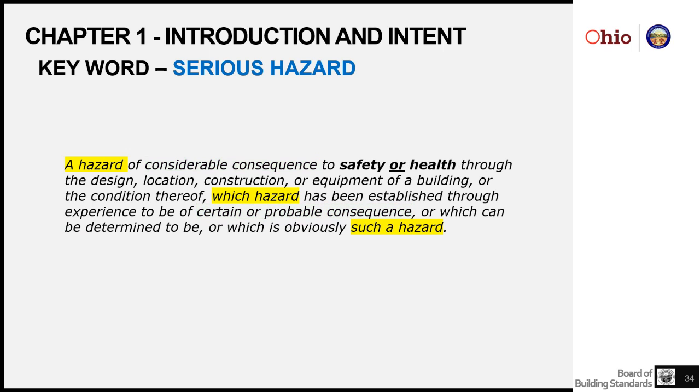It is a hazard that is going to affect safety or health, because that's what the building codes have the authority to regulate. They have the authority to regulate elements of safety and elements of health in a building. Generally, because a building doesn't have enough insulation, it may not be compliant with energy conservation, but that's not going to constitute a serious hazard.